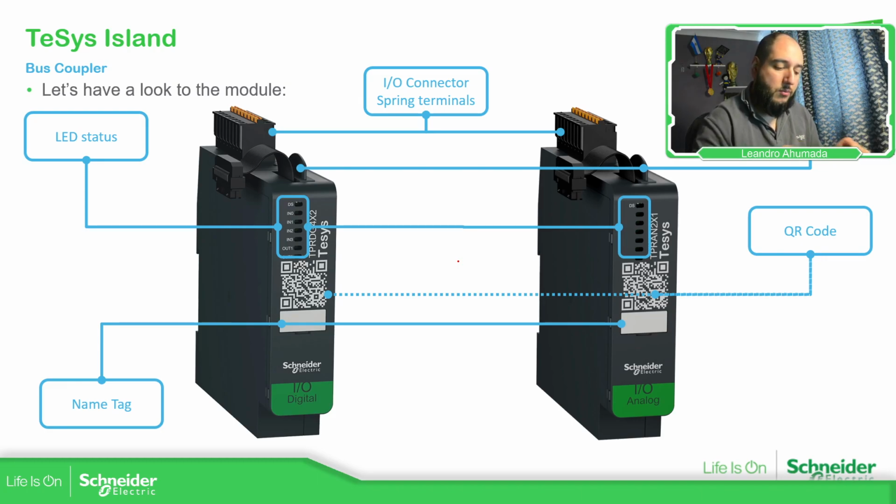In the top, we have some terminal blocks. If you have the information over there, you have input 0, 1. In this case it's the analog, but for the digital, it's very straightforward. It's going to be the same. You just need to have the common for voltage, for 0, and the 24 volts, and that's it.